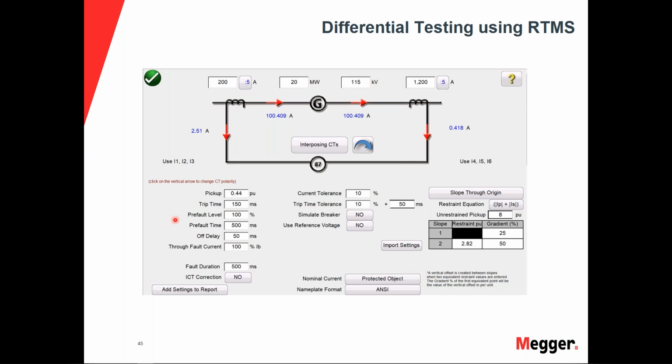I don't see a lot of electromechanical relays being used with this test template. Most of these are going to be used with microprocessor based relays, since we will be injecting 3-phase current, and so it would take 3-phase from winding 1 and winding 2.